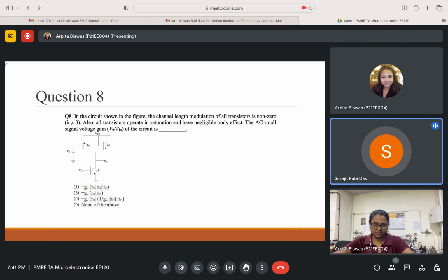And what is the current situation and the scope of this in India? Actually, device fabrication is in the developing stage. We procure some of the PCBs and give orders to companies like Micropack and Electrolytes, some from Hyderabad and Bangalore. They give us both the RF PCB and the DC PCB. For the RF PCB, we are using the Rogers substrate.